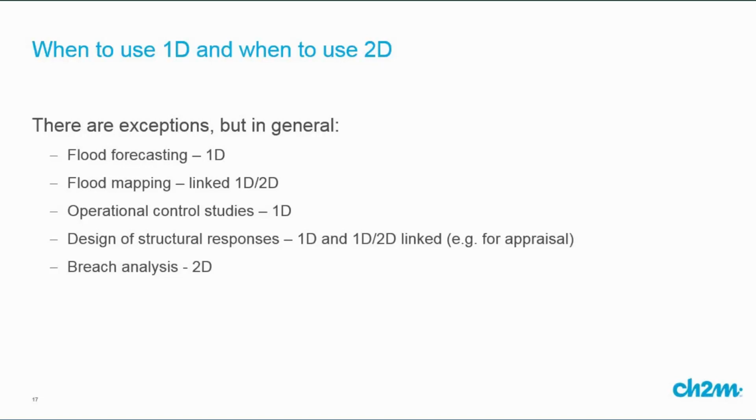Then if we're looking at breach analysis, where we've got holes in defences and things and water flowing out into the floodplain, usually 2D modelling of that breach flow, the inundation from that breach, is what's going to be most appropriate.